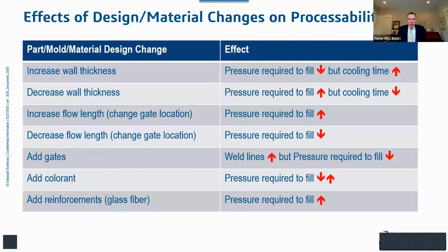Conversely, if I decrease my part wall thickness, if I determine through structural simulation that I can reduce my wall thickness by 10 or 15% or something like that, again, all things being equal, my pressure required to fill will increase.